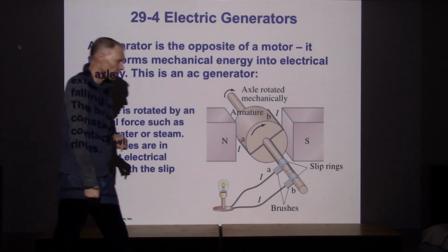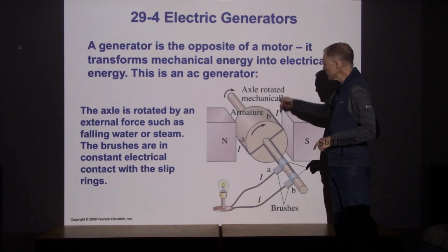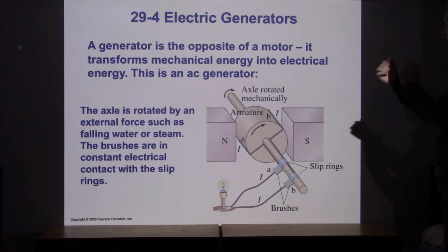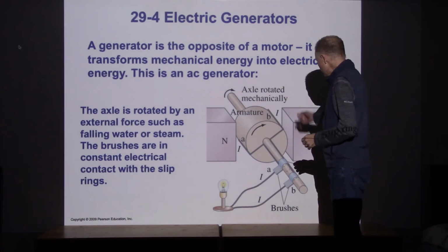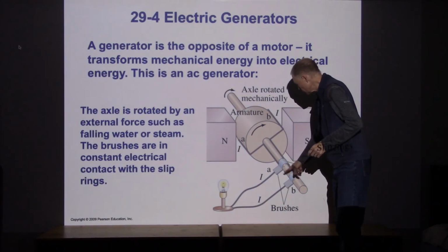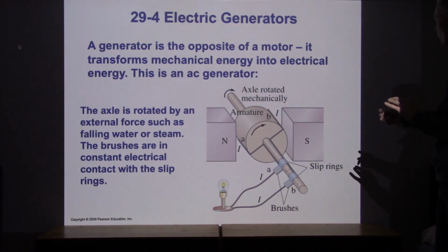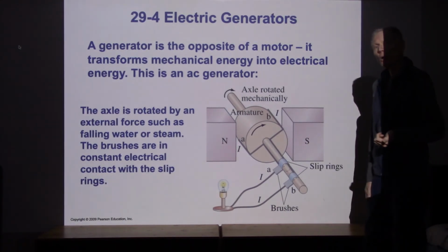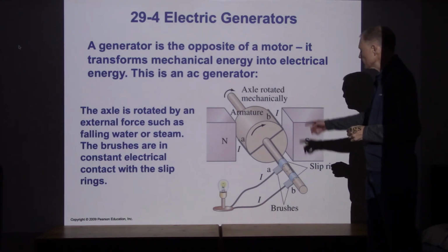Now we've already talked about electric generators as pieces of wiring that are being rotated through magnetic fields. And when you rotate through the magnetic fields, that's going to produce EMFs, first in one direction, and then back in the other direction. Now if I've got this generator that's rotating, I need to be able to make contact with those wires, and that's what these brushes are doing. So we've got some metal contacts, some brushes that are connected to the two ends of those wires, and as we rotate this through, we're picking up that alternating current. So this would generate an alternating EMF and an alternating current simply by rotating these rotors or the armature through the presence of these magnetic fields.